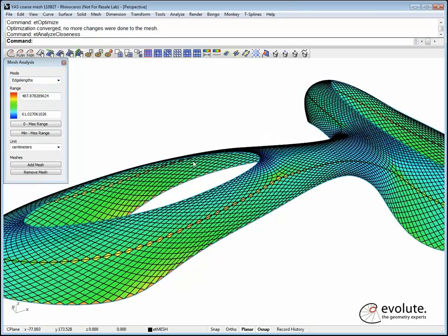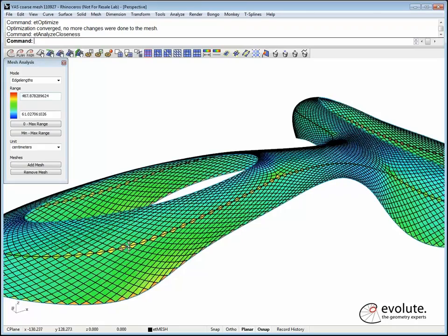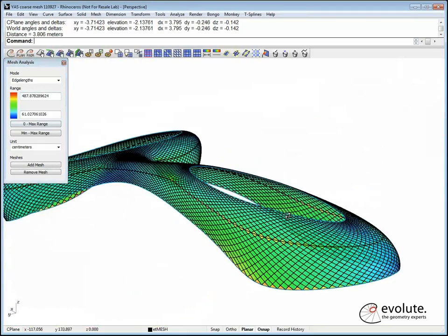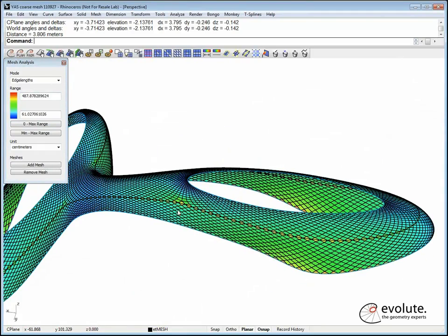Yeah, sure. I mean, we have these optimizations, the edge length and ideal panel. The ideal panel is, as Matthias said, in heavy development. We can analyze the edge length, of course, and these are real numbers, so we can actually have a look at these. These are 3.8 meters, so yeah, these are real numbers. Depending on these numbers, you might want to further subdivide your surface to get a denser pattern, or just have less subdivision steps in order to make the panels bigger.